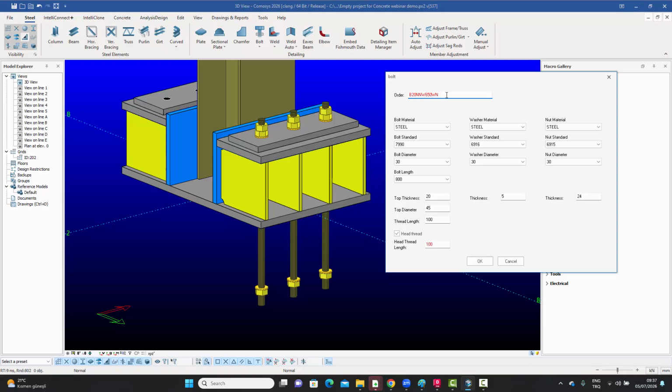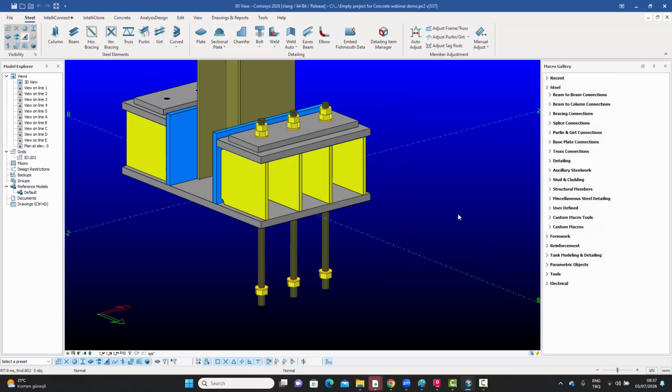And you can create, of course, multiple copies of multiple definitions, and you can create a thread on both sides if you want. So there's a thread on the other side, and you can give that, and you can modify the. These numbers are all taken directly from the database. And once you have this set up in your database, it's very easy to use.